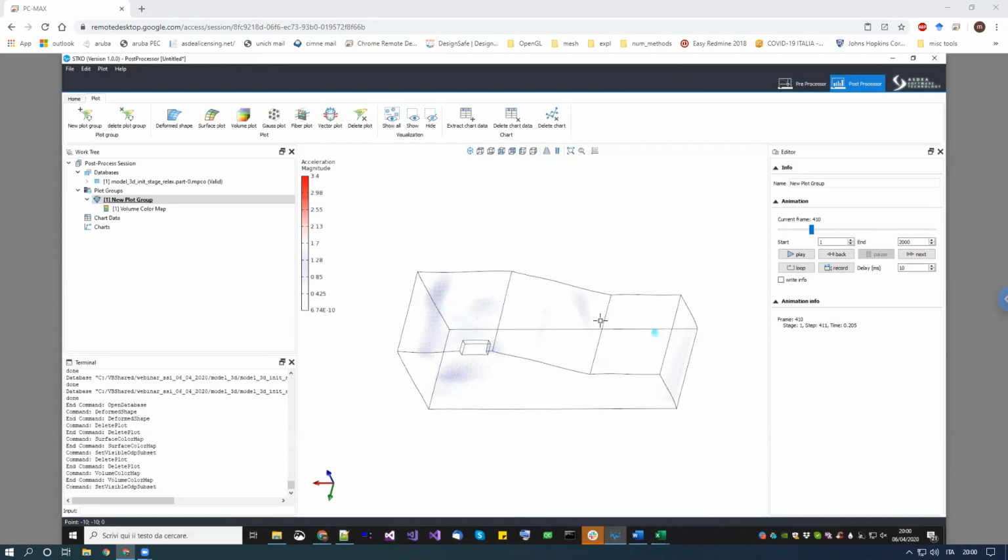But of course, a zero length element is just a collection of uniaxial materials. Then if you place this material in the direct component, translational component, or in the rotational component, it's just a matter of what you want to represent. A zero length element is just a collection of at most 6 materials for the 6 degrees of freedom of the spring. And actually, we have done this example exactly with the modified Ibarra in our previous webinar on lumped plasticity reinforced concrete models. So you can go back and look at our previous webinar. We are actually using the modified Ibarra-Medina-Krawinkler model in it.